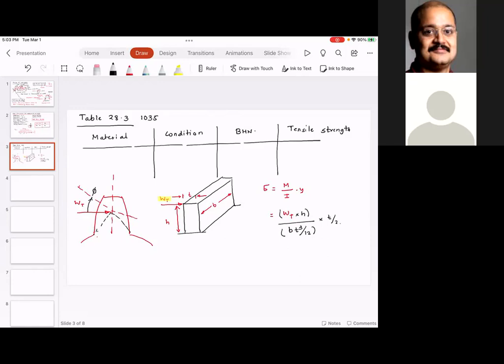Now what I'm going to do is, I'm going to make some simplifications and then find out. I'm going to take WT on one side. So WT is equal to, I'm going to call this sigma b, sigma b multiplied by b multiplied by t square, because check this out, there is t cube in the denominator, t in the numerator, so I have t square divided by 6h. Now here is something interesting. This t dimension and this h dimension, they depend upon m.